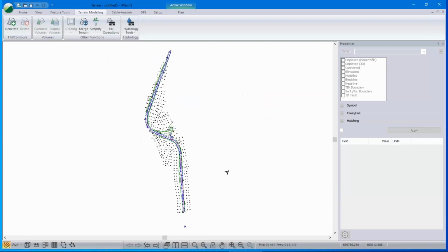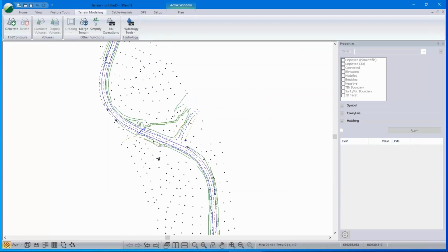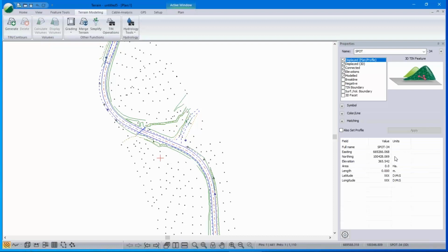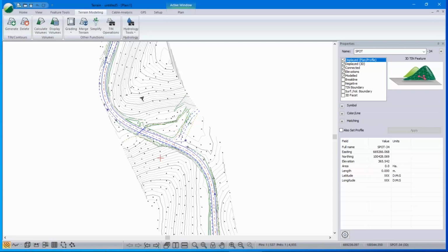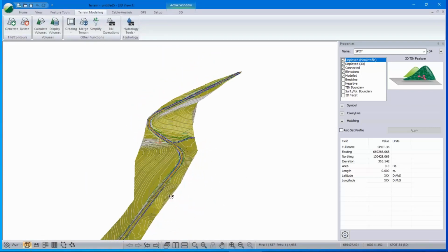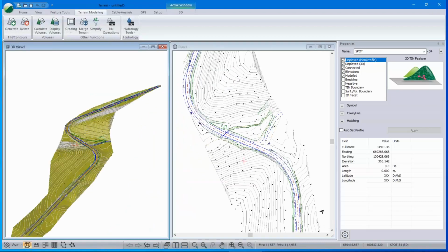There it is. And every point has a well-defined position, X, Y, and elevation, Z. And because those points are, first of all, defined as XYZ coordinates and tagged as modeled in the properties panel, we can make a surface. So I'll just generate a surface here, and there it is. We got contours all at once, and we can see that that's a nice three-dimensional surface.